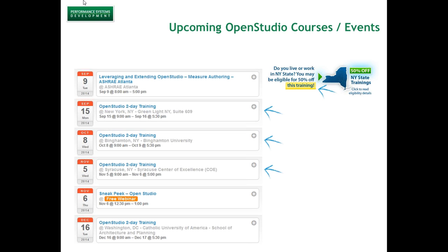So it's changing all of the walls in my model, the 7 or 6 wall sections that I had that were associated with those spaces. I get some feedback of what happened. It looks like it started off as an R11.8, and I moved it to R50. And if I accept those changes, I now have a model that has R50 walls.